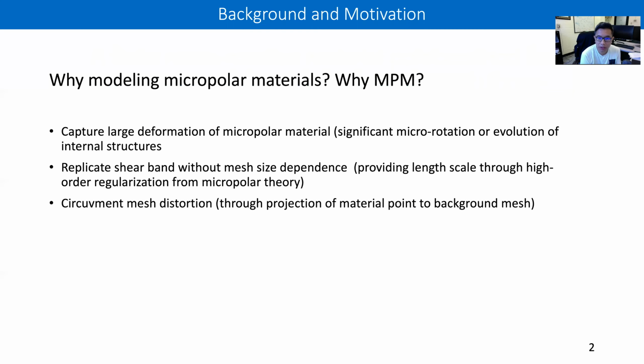So micropolar materials are materials that have inherent internal structure, and that internal structure introduces size effect. In the specific case of micropolar rotations, we would not only consider every other type of higher order kinematics, but we will consider the micro rotations of the material. And this could be helpful in capturing strain localizations where the internal physical length scale can provide a regularization.